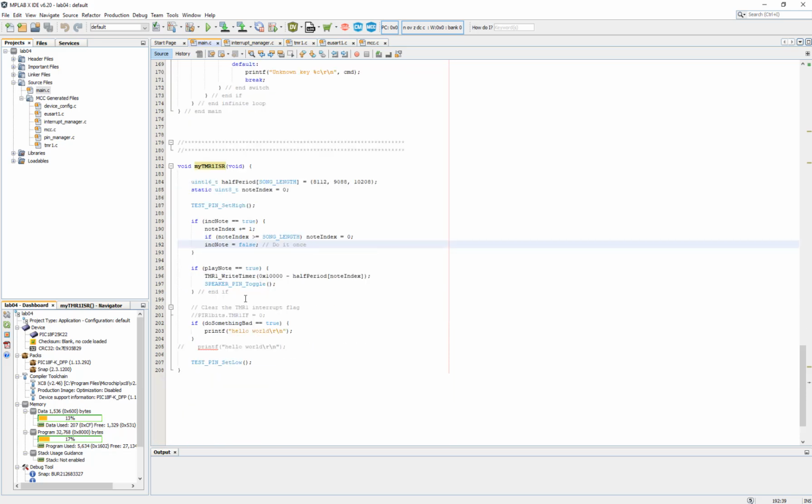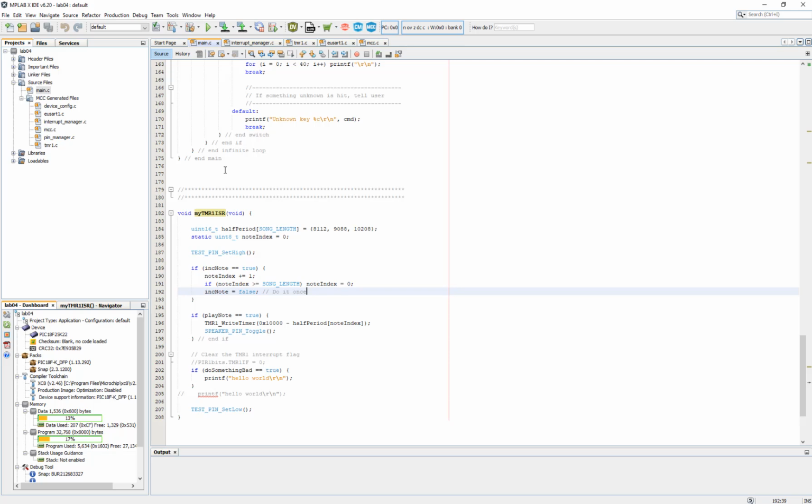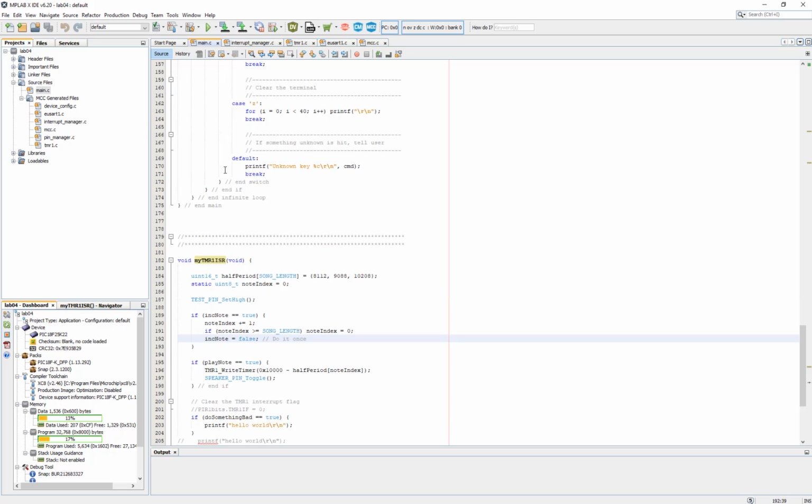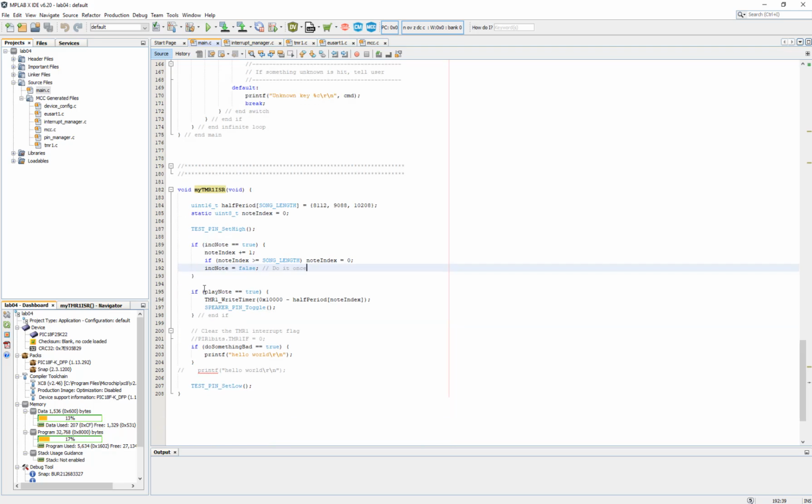I didn't bring my mouse, but what's happening for the interrupt? Like what I said in the lecture, we used that timer 1 interrupt to play the note, right? Every time it triggers the interrupt or turns on the flag, it comes to the ISR, which is at the bottom. You can open it up on your laptop. The same code is published on the website. It takes 4.1 milliseconds, like what we said in the class.